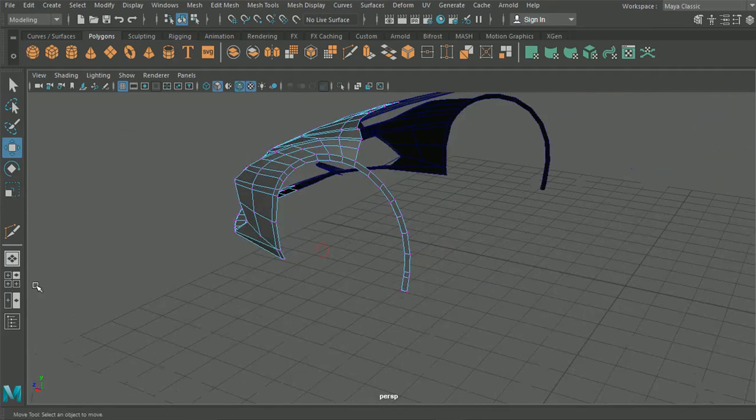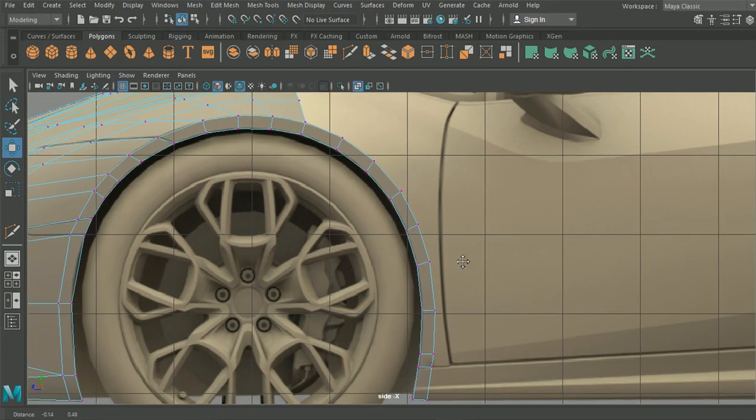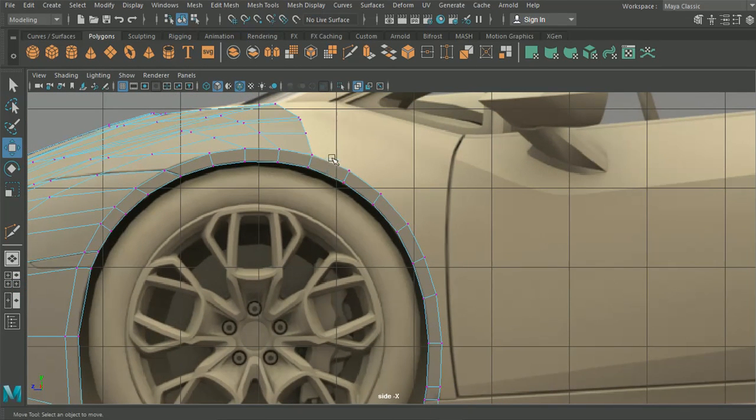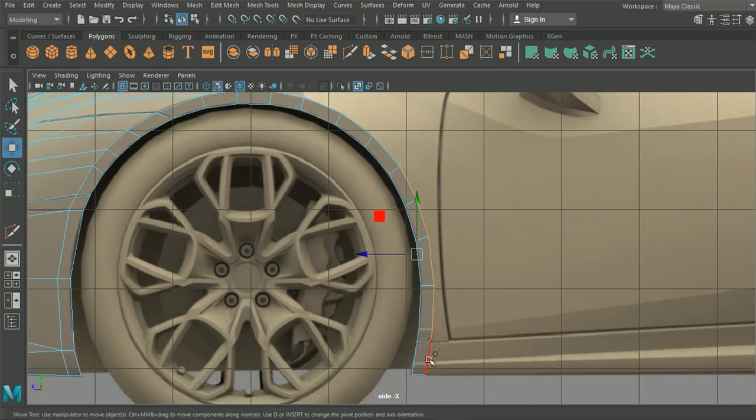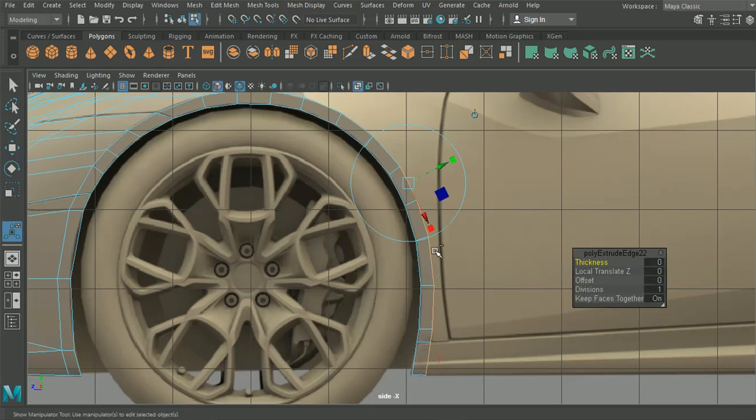Good. Okay, so I think a good, if we have this extrude up, this extrude up, this extrude up, and then we'll have these elements here extrude to the side. So we're going to select all those edges, Control E, hit on the world option, and we're going to pull those through here.